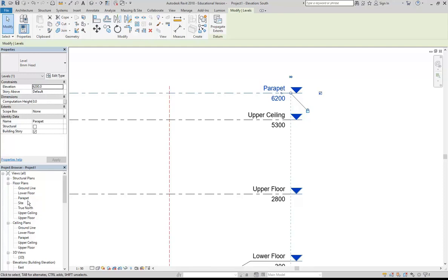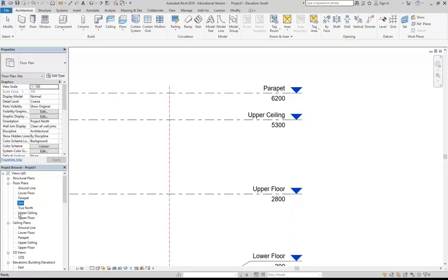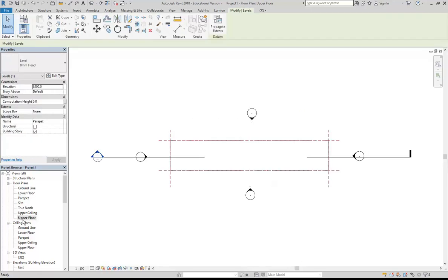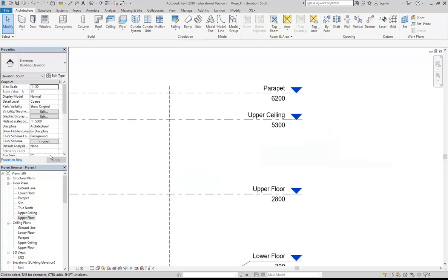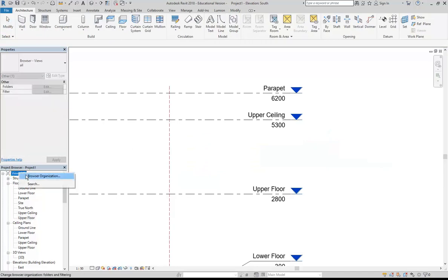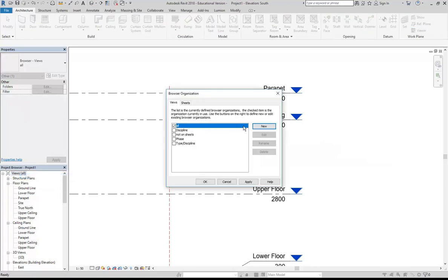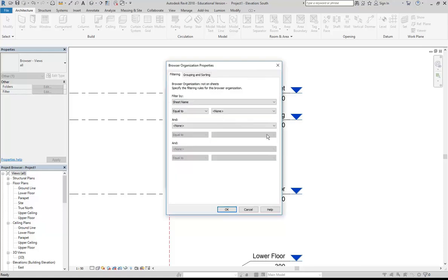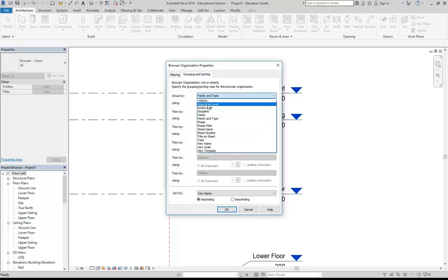And then you can see we've got a problem. Just for your ease of use, it's going to be much harder if they're left this way because they're not in order of height, which you'd probably want. Now, if you know some of the more advanced things in Revit, you'd know maybe that there is a way of setting the views to go by height. Okay, so there is a way. I won't go too far into it, but if you're wondering, there is an option for sorting by the level ascending, in other words.